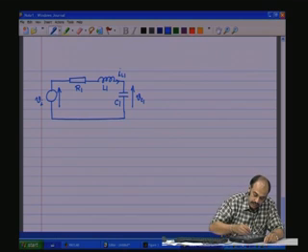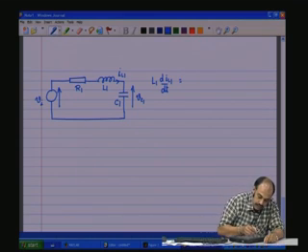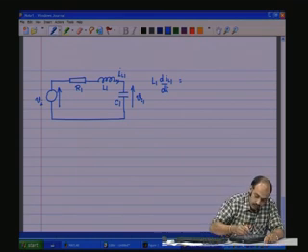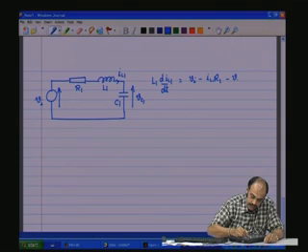So, let us quickly write the state equation. So, dIL1 by dt. Okay. You take across that one, which is L1 dIL1 by dt is the voltage across the inductor, which is Vi minus IL1 R1 minus Vc1.